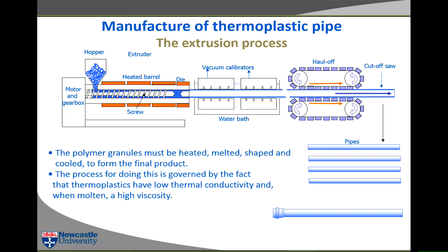It's fast-ish. What kind of temperatures are we looking at? Usually the material comes out about 20 degrees C higher than the melting point. The melting point of polyethylene, I'm sure it's in the notes somewhere, but if you just want to write it down, is 130. The melting point of PA11, I think, is 220. I might be wrong there. The melting point of PVDF is 185. So you get it up to a higher temperature. You don't want to get it just to its melting point because you need to heat it higher to lower the viscosity of the material.